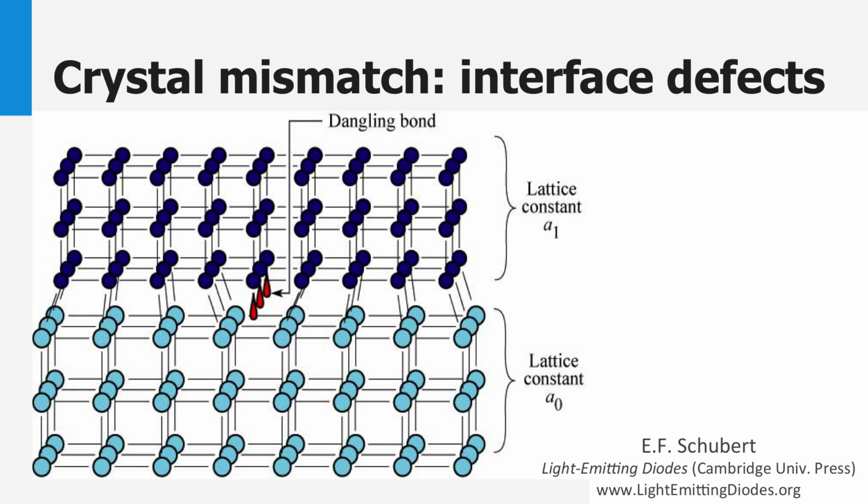There are no two different semiconductor materials that have the same bandgap and the same lattice constant. This means that interfaces between these materials show a mismatch. Not every valence electron is able to make a bond with a neighbor. However, the triple junction I have introduced earlier, based on gallium indium phosphide, gallium arsenide and germanium, is a lattice-matched solar cell. What do I mean with that?